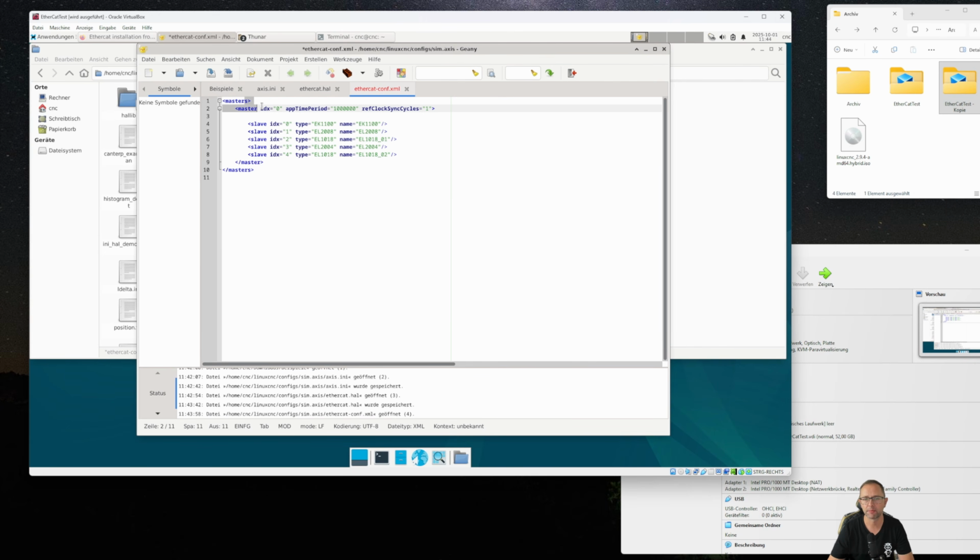That means we have a master that runs in the reference clock, that is in the servo thread. And inside there are some participants that are now described rudimentarily on the right, because we have already included the drivers. This means that when I write it in here, EtherCAT already knows what's going on, because there are already drivers for these devices. Someone sat down and wrote drivers.